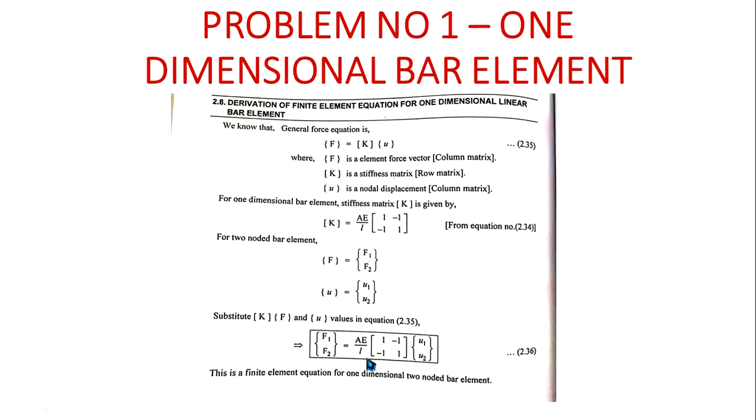You will be given a problem with a physical structure and a boundary condition. How you divide the full structure into a number of small elements depends upon a few conditions. You need a minimum of two elements, never fewer than two. As the number of elements increases, the approximation of your solution improves.